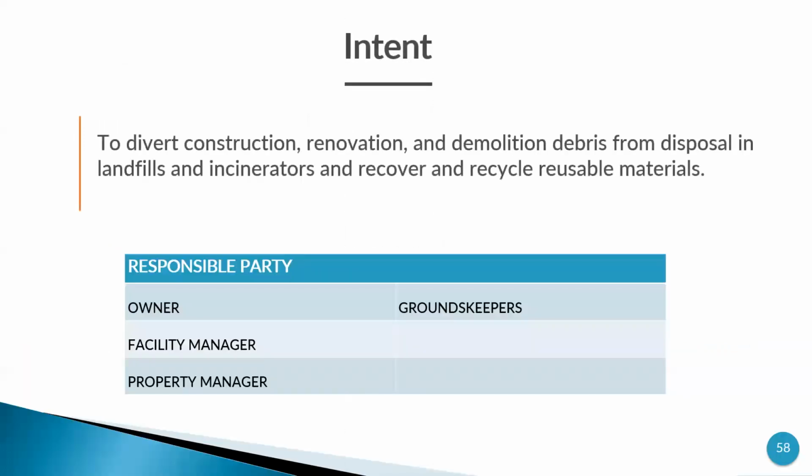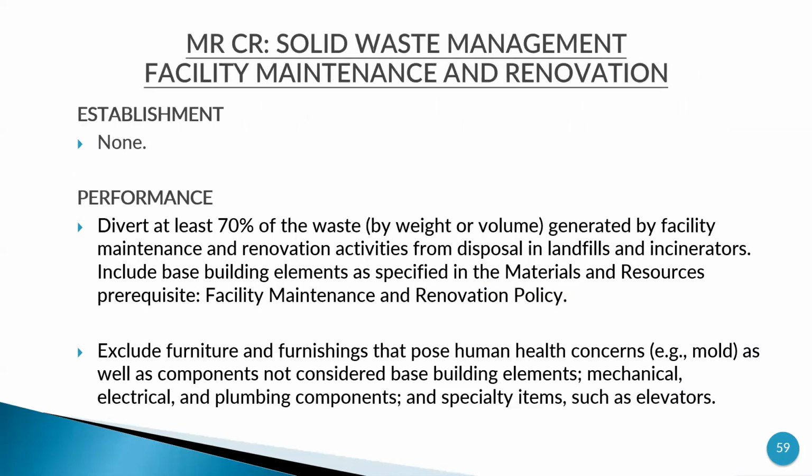In this, to divert construction, renovation and demolition debris from disposal in landfills and incinerators, recover and recycle usable materials. Establishment we have already covered in the prerequisite. Now we are talking about the performance. Here we have to divert 70% of the waste, again by weight or volume, that is generated by facility maintenance, that is during renovation, from disposal in landfills or incinerators.